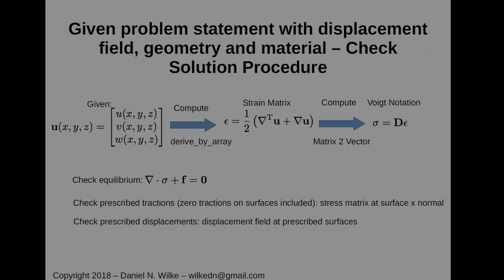Okay, so that is essentially important to understand, that where we have prescribed displacements, there's additional tractions we can go and check. Okay, but first off, this is just checking the stuff that we claimed we've applied. Okay, and then we have the prescribed displacements, and then we need to make sure that the prescribed displacements are what they claim to be. Okay, so if we claim that prescribed displacement here is so many millimeters or so many microns, or if it's zero on a face or zero at a point, then we need to check that it's indeed true.